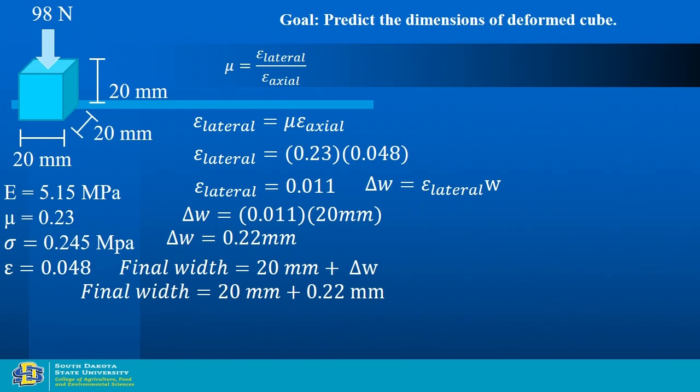I mean, volume is the same, right? We are assuming that it's an incompressible material. No, it's not. It's a compressible material because the Poisson ratio is 0.23 only. So that is why we probably lost some of the deformation, right? With a 0.23 Poisson ratio, there are a lot of pore spaces, air spaces there. So when you compress it, more goes down and less comes out.